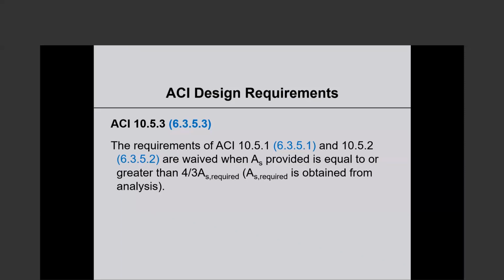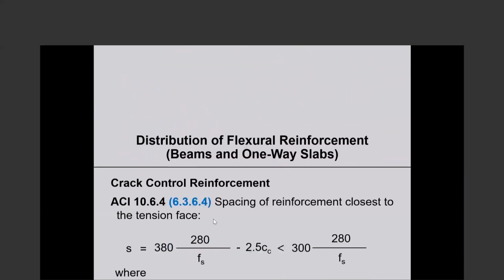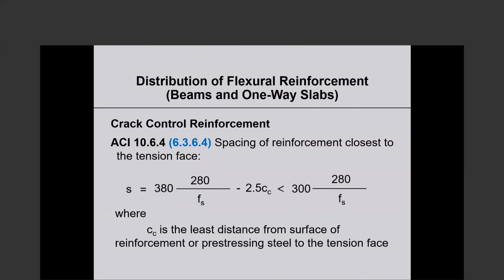And how much reinforcement is required is obtained from analysis of the structure under the service level loads that we are trying to carry. Okay, so this is a very, very important exemption that we try to take advantage of when we don't want to provide minimum reinforcement.